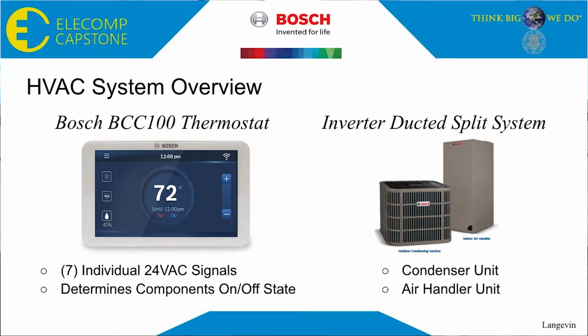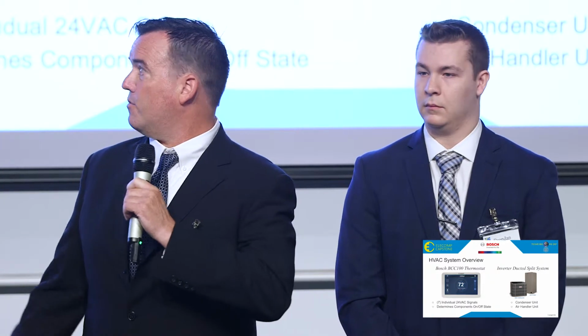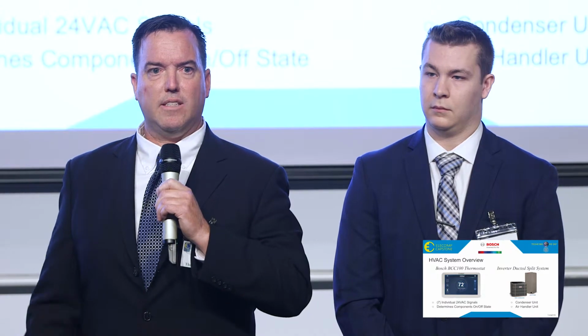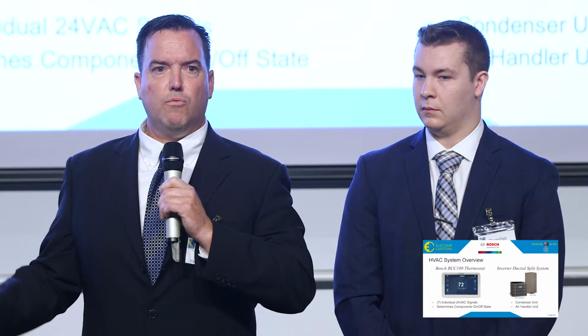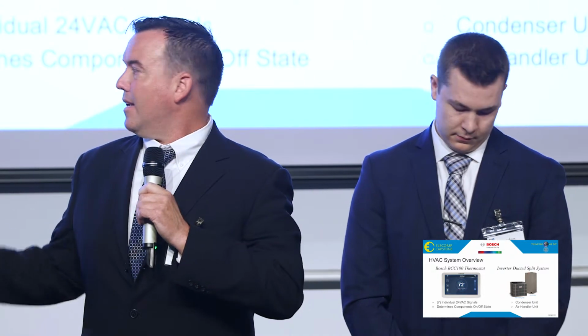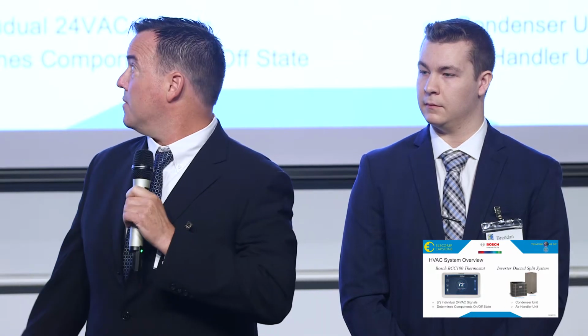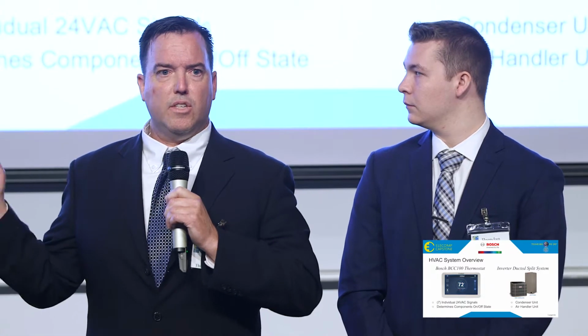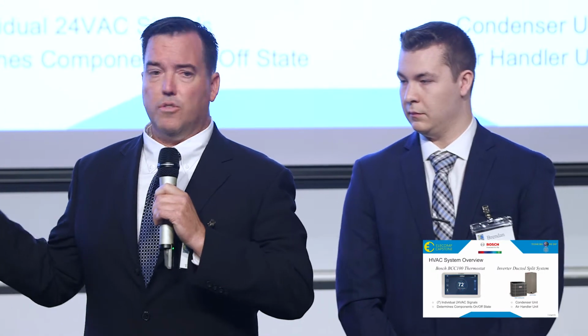So the HVAC system overview and what we started with is the Bosch thermostat and the inverted ducted split unit. The thermostat is capable of handling 7 individual 24-volt AC signals that it sends out to the HVAC unit. With built-in relays inside that thermostat, it handles the on-off state of all the components inside the HVAC unit. The IDS unit consists of the condenser unit and the air handler unit, and uses 4 out of the 7 signals coming from the thermostat.